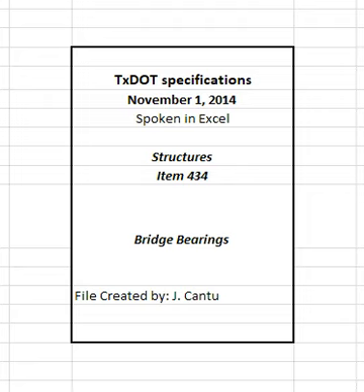Provision for sliding movements, if required, uses a separate steel top plate with stainless steel facing, upper component, bearing on a lower component, and a lower component with a layer of PTFE bonded to the top of the upper steel bearing plate of the HLMR assembly. If required on the plans, restriction of lateral movement is provided by guide bars integrated with the steel top plate and interface components of the same stainless steel facing and PTFE layer.